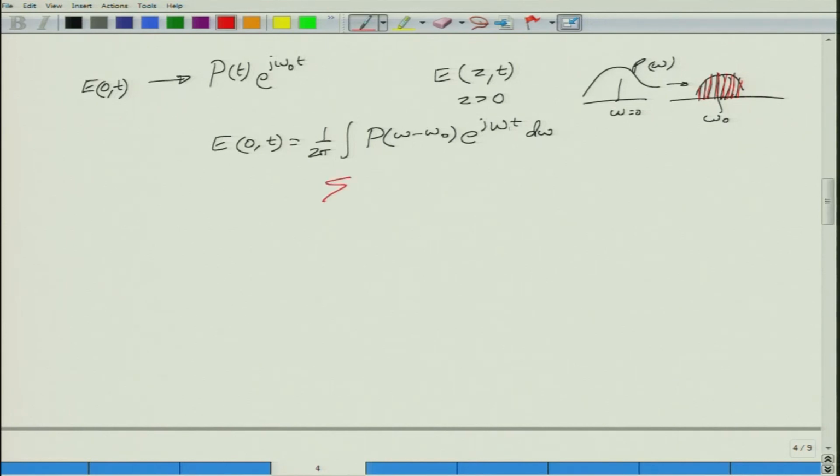So, intuitively this is many frequencies each having an amplitude. So, instead of considering this as a function, now consider p of omega k minus omega 0 as the amplitude of the kth frequency, right, d omega. If you think of it this way, what you are doing is putting many sinusoids of different amplitudes together. Now, that is essentially what Fourier analysis is telling you. Okay.